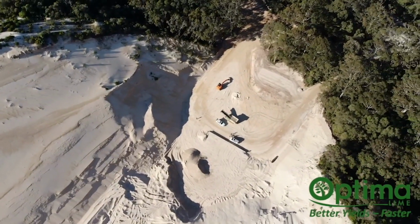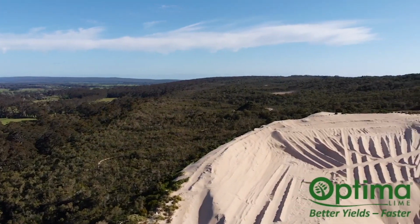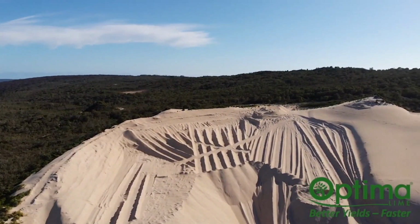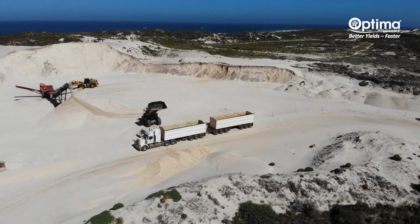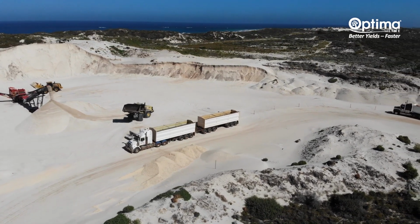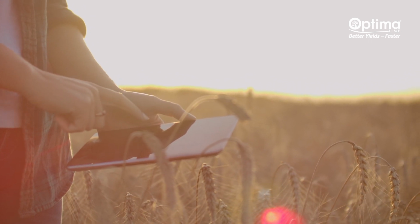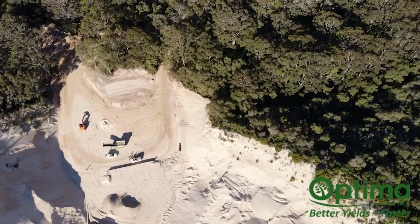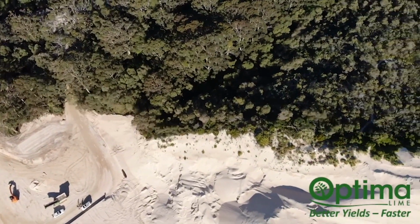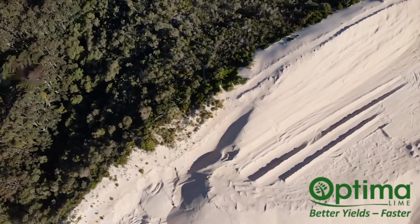With the benefit of our experience, we'd advise, make sure you check the specification for the pit from where your lime is coming from. Check you are getting an up-to-date spec, not one from last year or the year before. You shouldn't have to provide your personal details to get a basic product specification. Choose a pit that has historically high-level specifications. It's a natural resource, and so one-off tests can be anomalies.